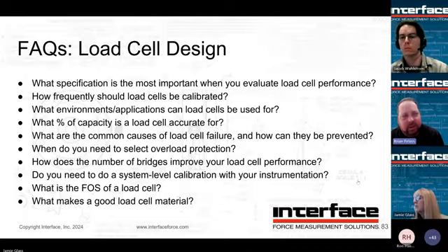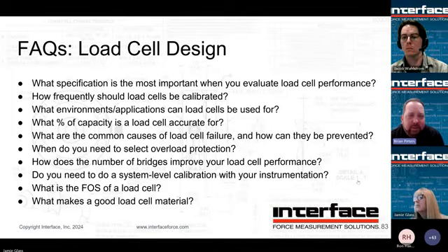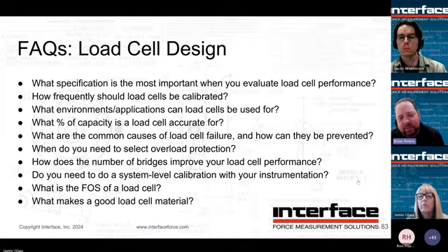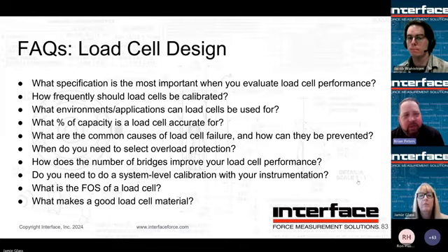If you're more concerned with the torsional bridge, then you'd want to start with one of our 5600s, which begins life as a 5400 reaction torque flange sensor, and then we add axial bridges to it. So typically the best thing to do if you're very concerned about crosstalk is to characterize it. Do some applied loading, see how it impacts the signal, and then adjust for it in your instrumentation.